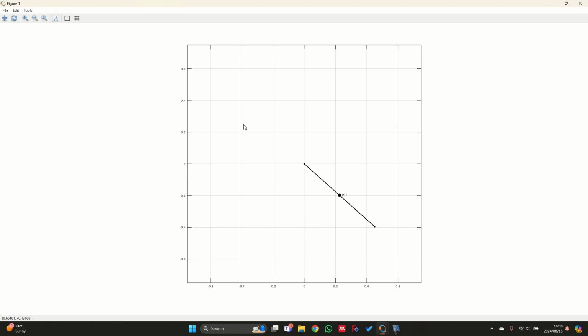So the inverse dynamic analysis problem that we did actually gave us information about how we can perform a forward dynamic analysis problem as well. If we are interested in having this system move in the counterclockwise direction, then we need to specify a torque that is larger than 5.9 or perhaps 6 Newton meters. Okay, so we're just going to wait for this one to finish.